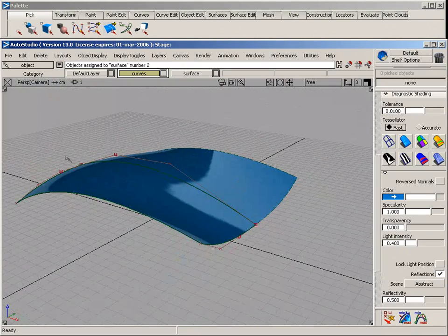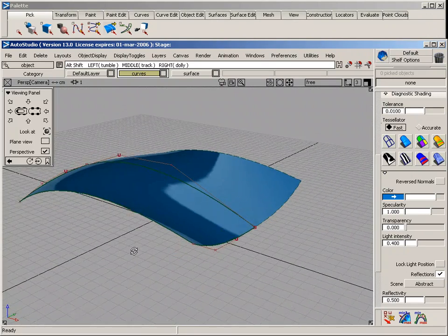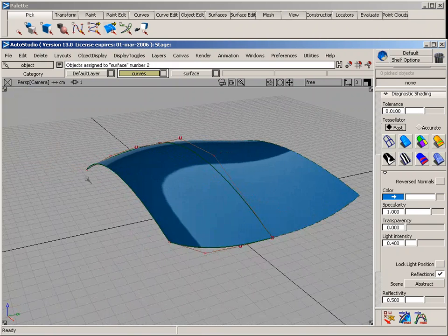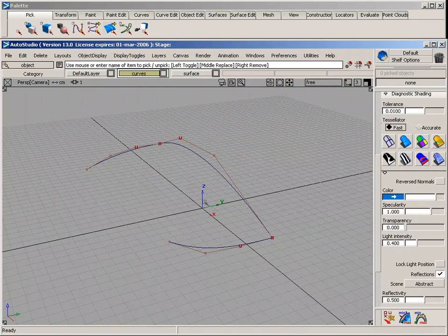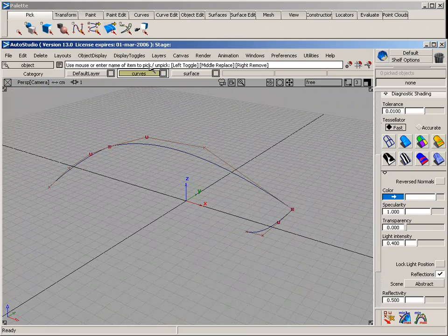In this particular case, we control 3 edges. However, there are cases where you may want to even change the 4th one. For that, you can use a rail surface that's using 2 generation curves.